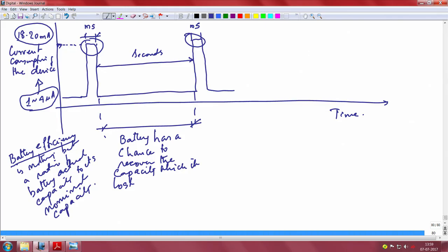See, if you do not want this battery to have high current discharge periods, this spiky nature of drawing a significantly high amount of current, because the battery is discharging quite rapidly when it is sourcing this kind of high current, and you want to avoid high discharge and yet deliver the required current to the load, what you can think of is putting a capacitor at the output of the battery.